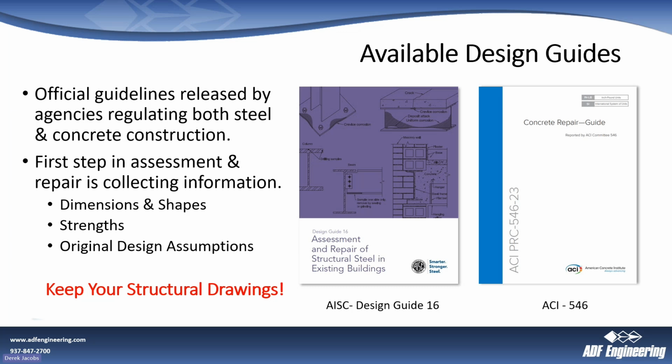I think when we go to a site, our first step in the assessment is collecting information, which includes dimensions and shapes, steel shapes, dimensions of beams, lengths, the strength of the materials, and determining what the original design assumptions were for any structure we're looking at.